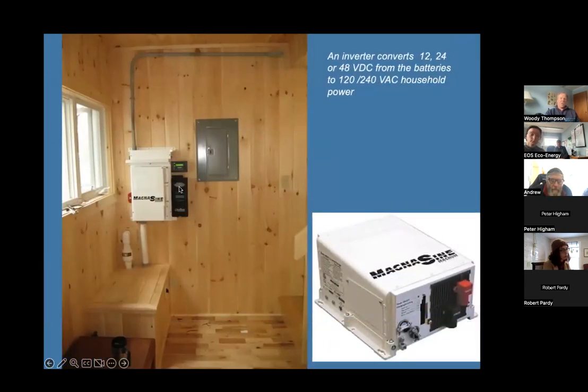This is the inverter charge controller, to communicate with the inverter so that you can tell it when to turn off the inverter in case your batteries get too low. So you could set that at, if it was a 12 volt system, you could set it to like 11 volts or 10.5 volts. This conduit carries the conductors from the solar modules. And this is the load center with all the breakers in it. This system was installed in Nova Scotia.